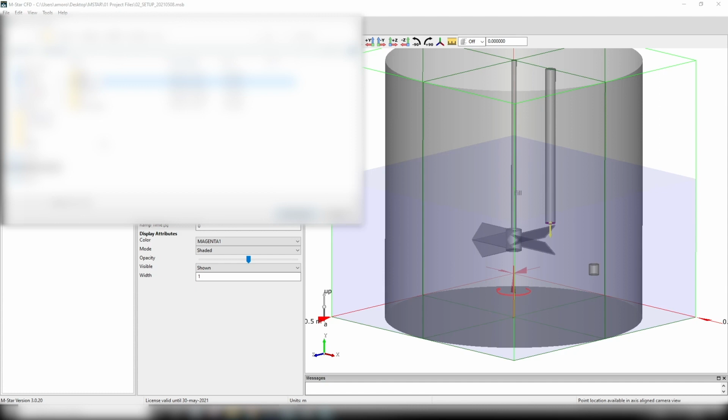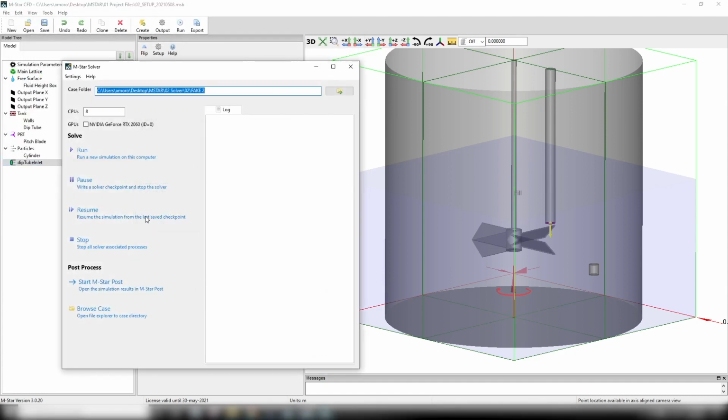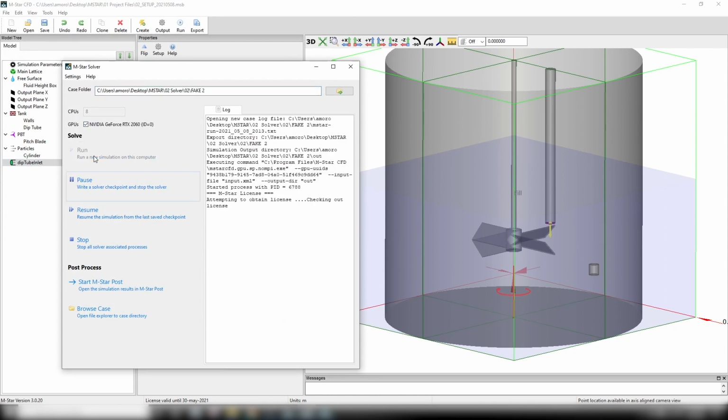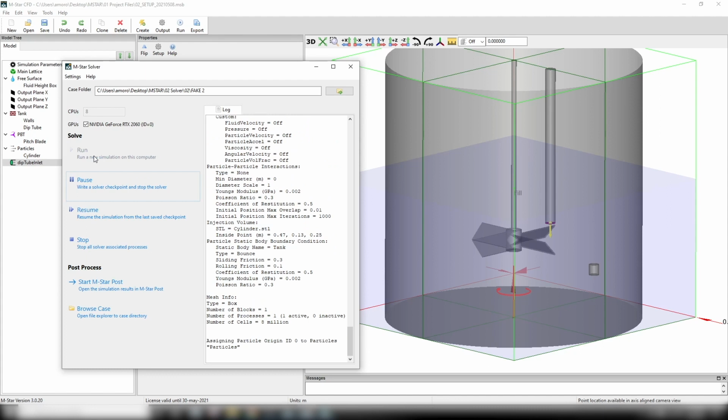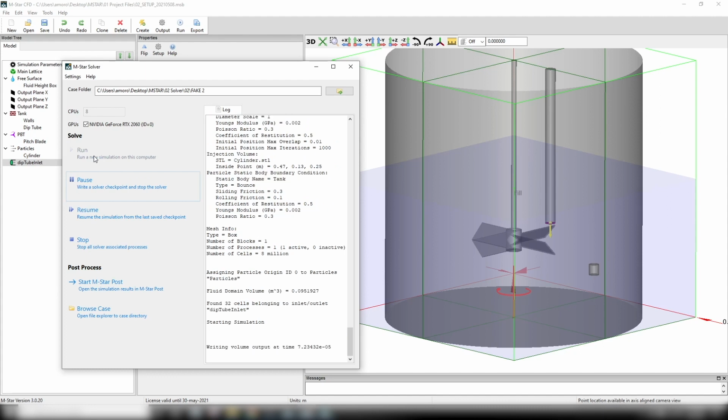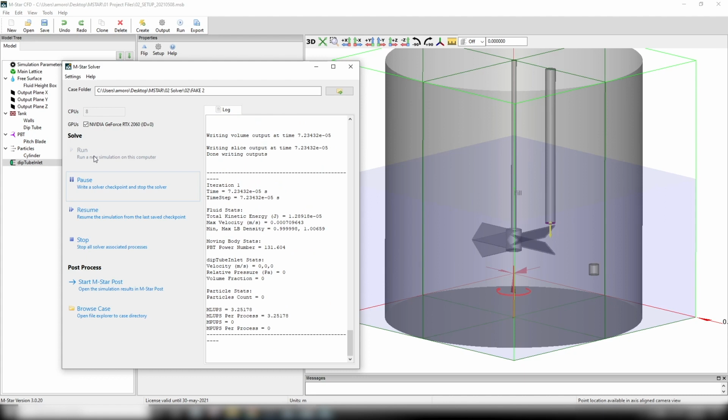Because the free surface is active, the total fluid volume will increase by 15 liters as a result of this fluid addition. The position of the free surface will change as a result of this fluid addition. Note that flow rates can be negative, implying fluid leaves through the outlet. Also note that the flow rate can be arbitrary user-defined functions. We will keep all of the simulation parameters the same, and we will rerun the simulation.